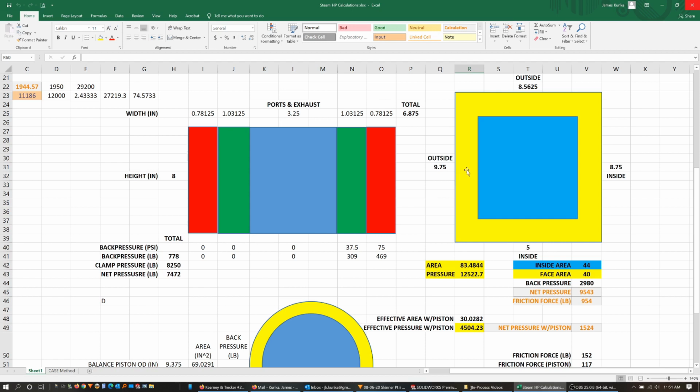Well, basically there's an analog equivalent that if the pressure starts out at 150 psi here and goes to 0 here, it basically forms a triangle and it just bleeds off linearly. So you can look at the area in yellow as if it has the average pressure of 150 plus 0 divided by 2, or 75 psi on it.